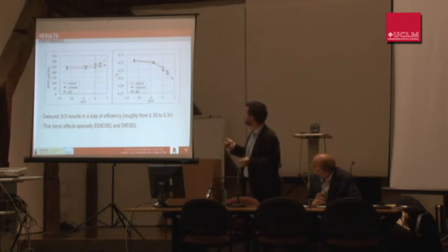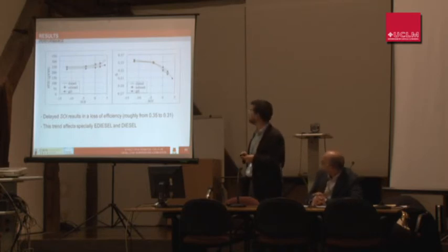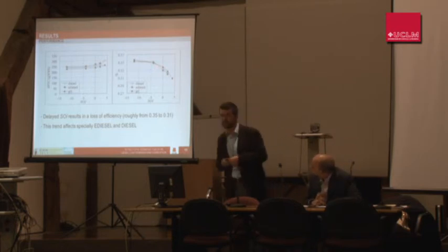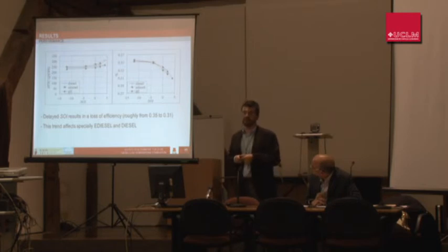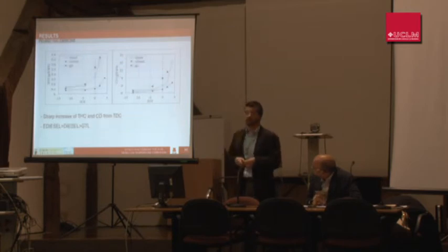But with the efficiency, the energy content does not have influence, and we see that the fuel efficiency decreases when delaying start of ignition, which is expectable since we are delaying the combustion process from a centered one. So we are deteriorating the efficiency.